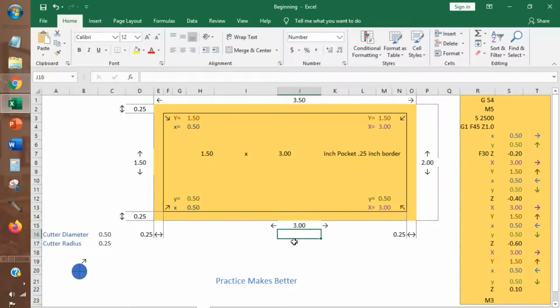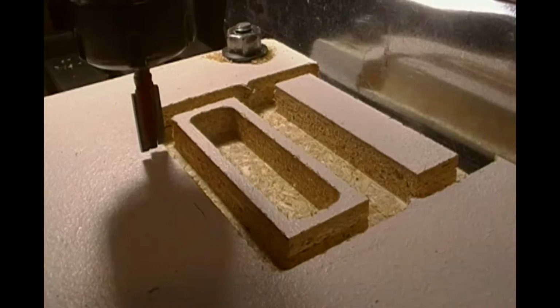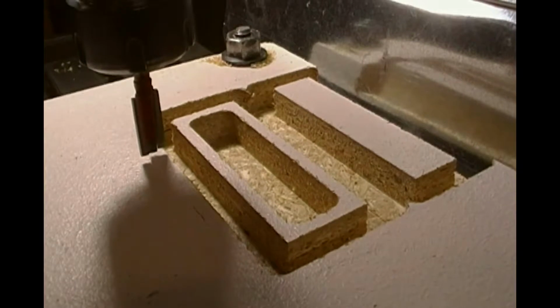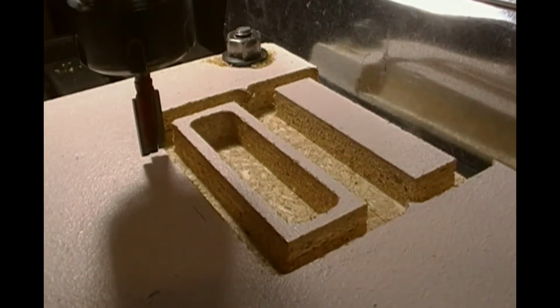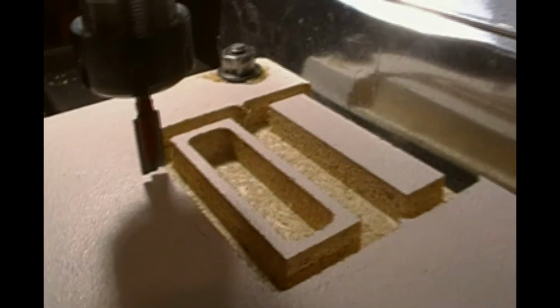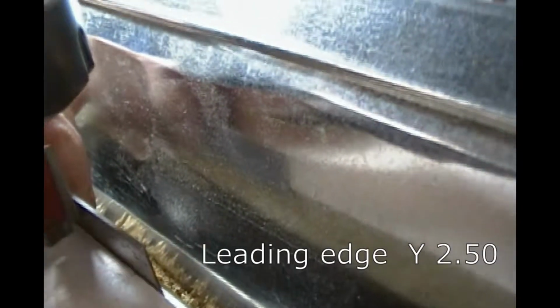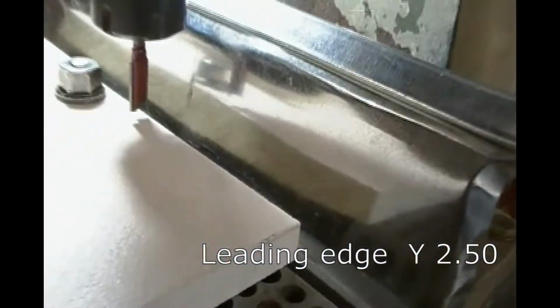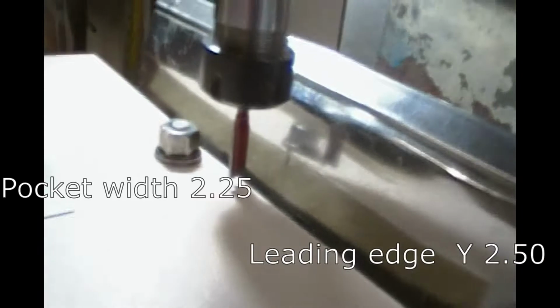There are many different methods to zero X and Y axis before cutting. One method is to use a straight edge to align the leading edge of the cutter to the bottom edge of the workpiece, then set the DRO coordinate to minus 0.25 inches. A second way is to align the leading edge of the cutter to the top edge of the workpiece, adding 0.25 to the pocket's top Y coordinate.